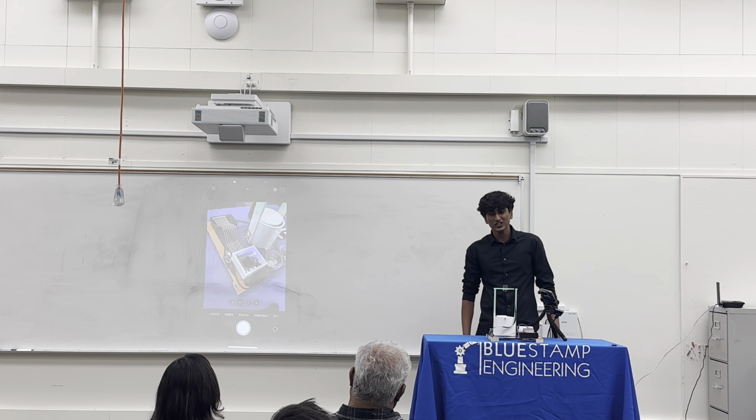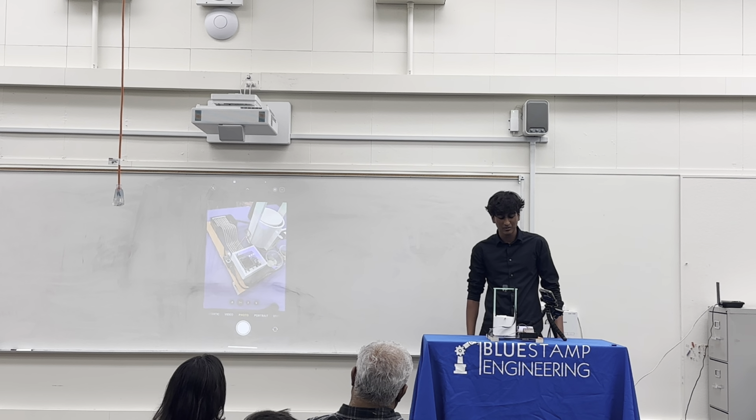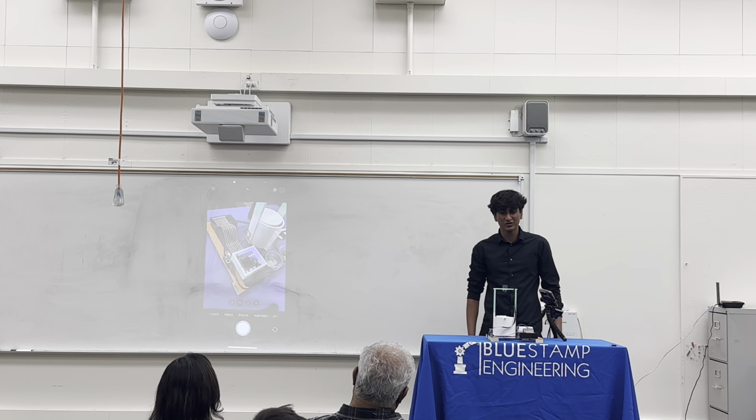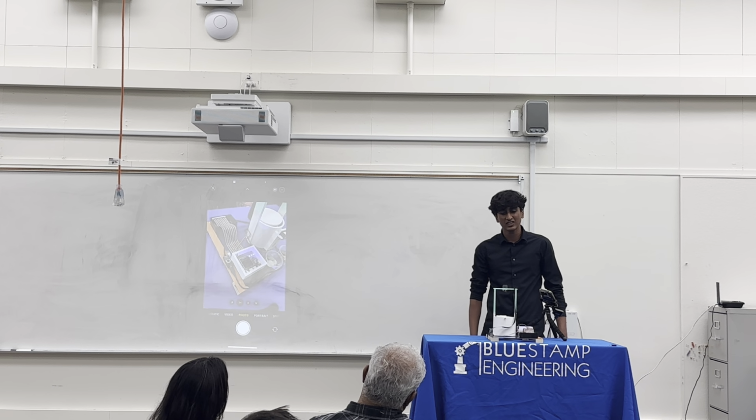At first, I tried training the model by downloading images from the internet and uploading them to the Teachable Machine website, which is the website that I used to train the model. But that didn't really work because the camera that I have is really blurry and it couldn't tell the fine details that were on the downloaded images. Then I tried using my phone camera to take pictures of the coins, but that also didn't work because the Pi camera was really finicky. So I ended up having to take pictures on the Raspberry Pi camera itself, so I made this script that takes 5 pictures every second when I hold down the spacebar.